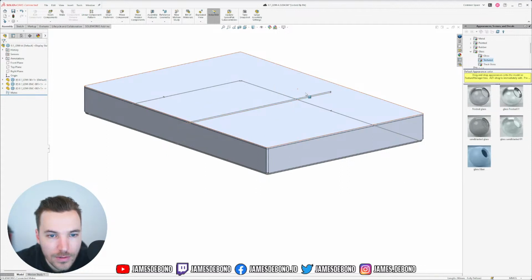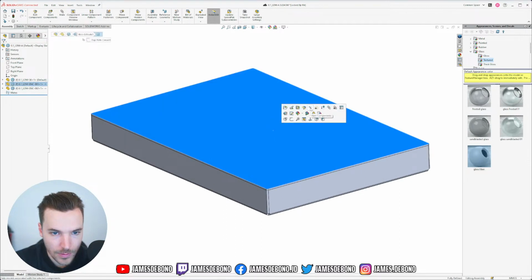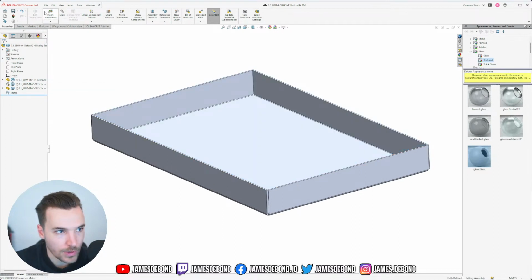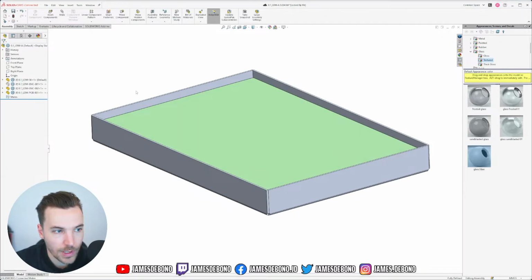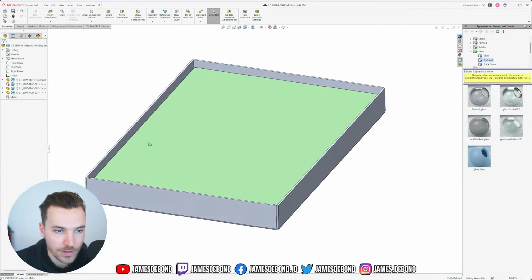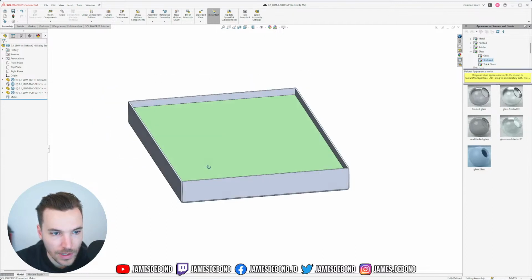Okay, so I'm gonna hide all these sketches. I'm gonna hide this, and then I'm gonna insert the PCB. Boom. Now, because everything is linked to my skeleton model, my skeleton sketches, when I drag this in, I don't need to do any mates.